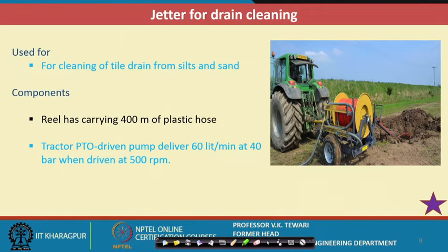As it is transported over a length of the channel, you will find that at some location, depending on its velocity, it will start losing some of its particles, and that will start silting and depositing material, which will create a base and thickness in the drain, and that will reduce the capacity of the drain.